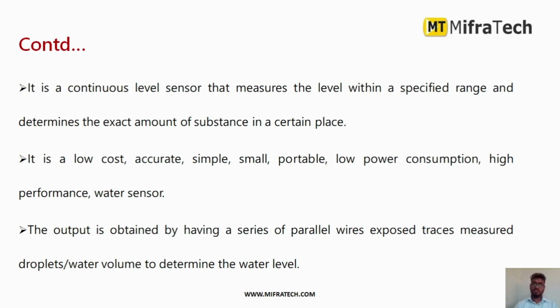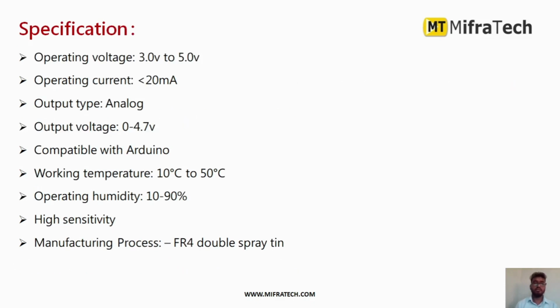As you can see in the water level sensor, there are parallel lines. Based on those lines, depending on how much of the sensor is immersed in the water, the conductivity increases. Based on that, it measures the water level.